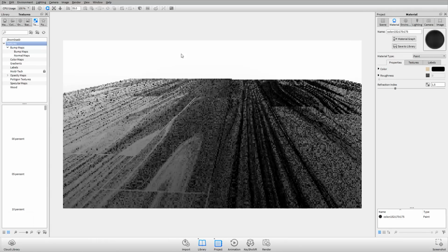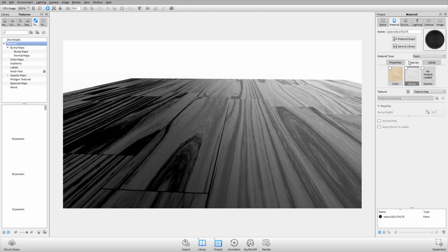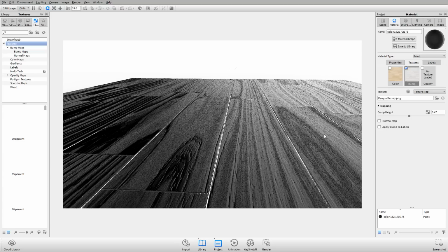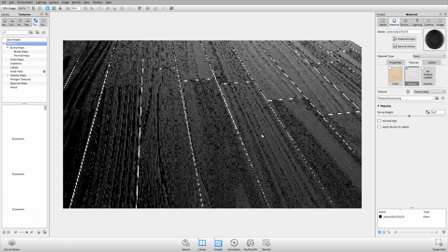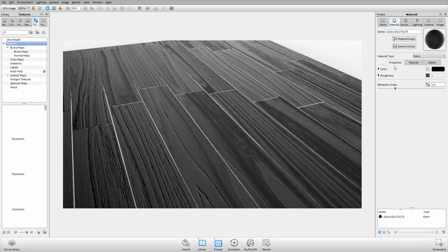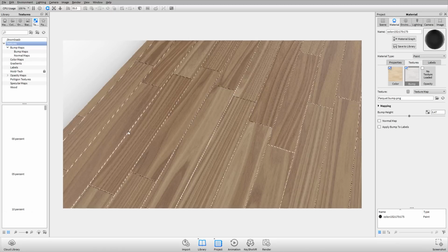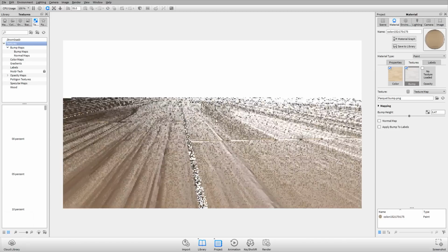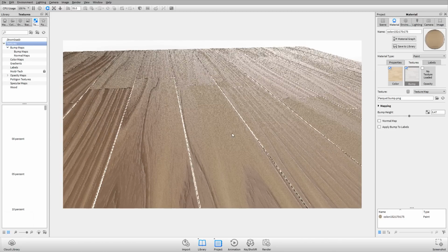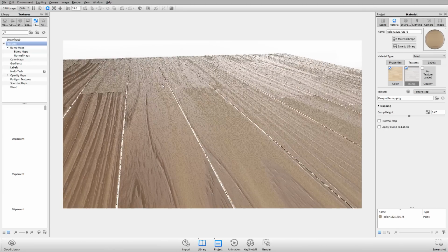So as I rotate the environment around my model, you can see that this is a really interesting way of picking up my shadows and my highlights. Or sorry, just that it changes the gloss. Shadows and highlights are when I throw on a bump texture on top of this. So this one, even without a color texture, is going to give me a really interesting appearance because I'm again defining that roughness using an image. If I then throw the color texture on, right now I'm getting a really nice looking wood material just by throwing kind of 3 textures on.